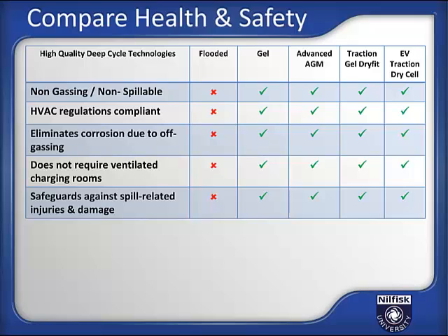It's either immobilized into the gel electrolyte and the gel products, or it's immobilized into the glass mat material of the AGM and the EV traction dry cell. And so that's why the flooded does not receive a check mark for safeguards against spill-related injuries and damage, and the sealed valve-regulated lead acid batteries do.